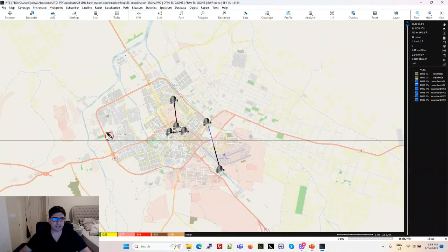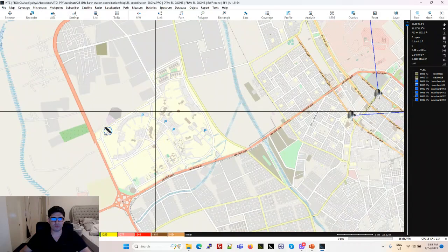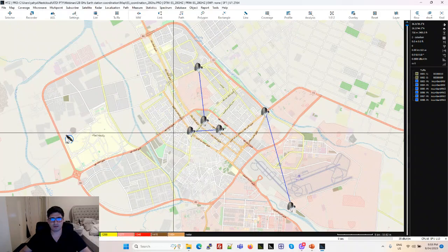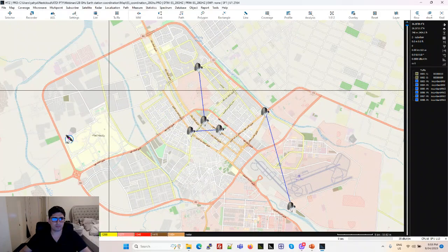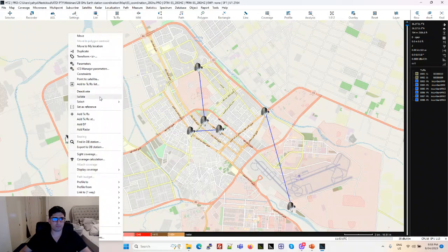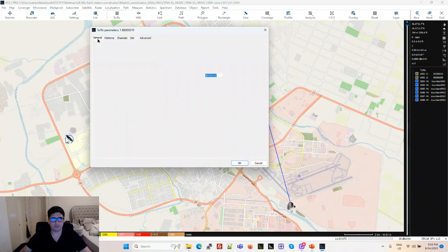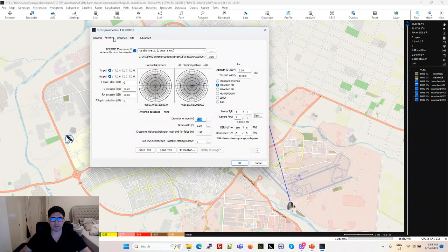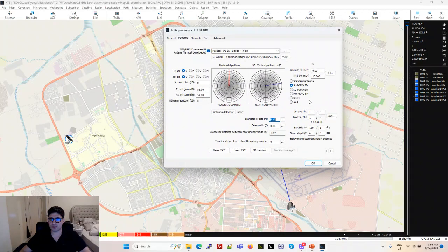Okay, so that was really just a quick analysis of the impact of this earth station on these microwave links. The tool is going to spread the power over the bandwidth when calculating the interference analysis, and it's going to automatically steer the antenna pattern for the potential orientations that we defined here.